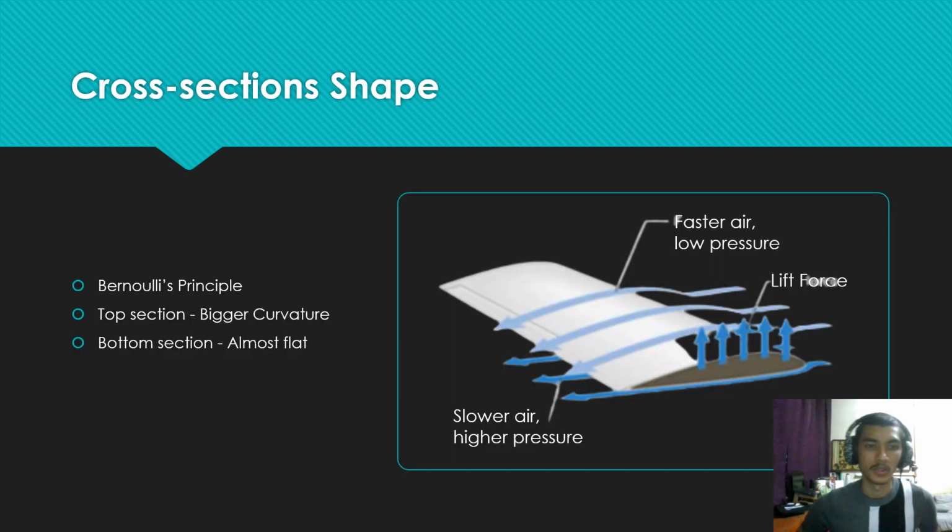According to Bernoulli's principle, a fluid that travels at a higher velocity generates lower pressure. Based on this theory, the streamlined shape of our model is aerodynamically designed so that the wind travels faster over the airfoil and slower below the airfoil. The pressure difference between the top and the bottom generates the net lift of the airfoil. So the bigger the pressure difference between the top and the bottom region, the higher the lift force that will be generated. In order to maximize this effect,